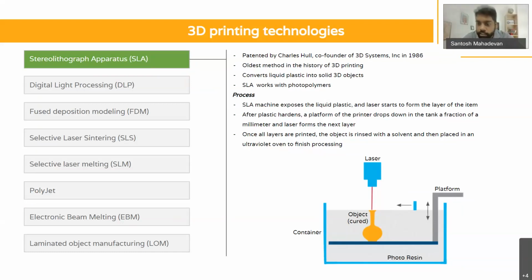So wherever the laser touches the photopolymer is naturally going to get hard, or form a rigid object. The parts where the laser does not touch the photopolymer, it does not cure. This way the first layer, the 25 by 25 square, is going to be formed.